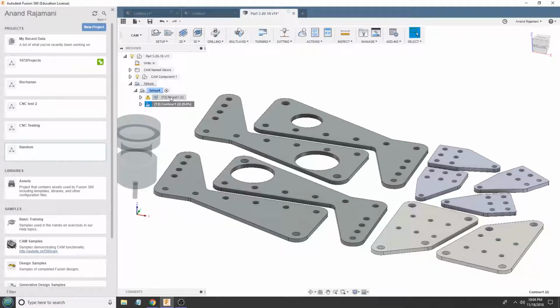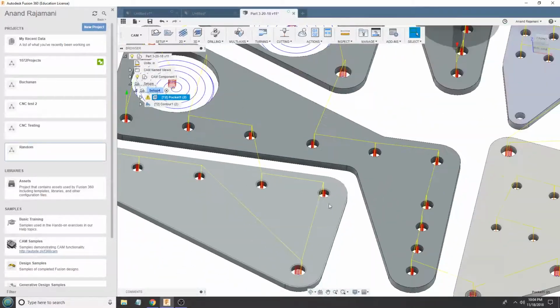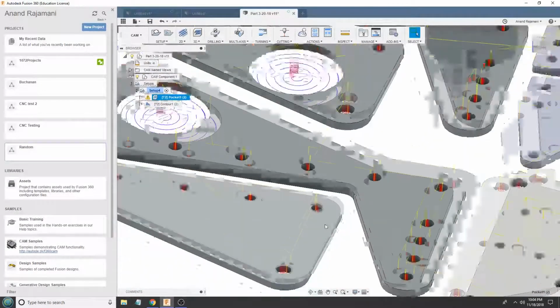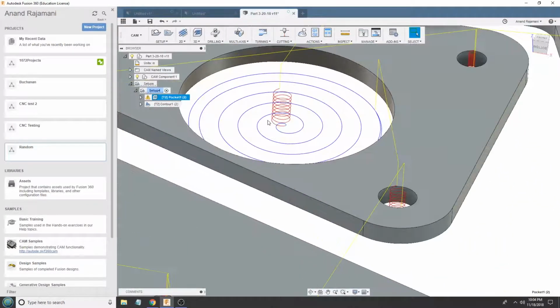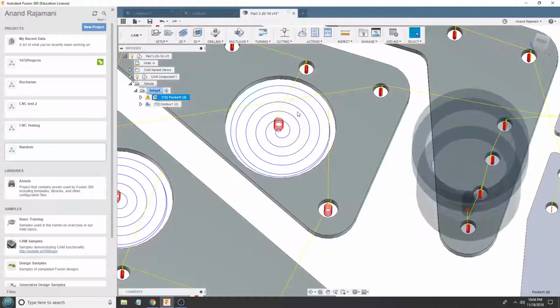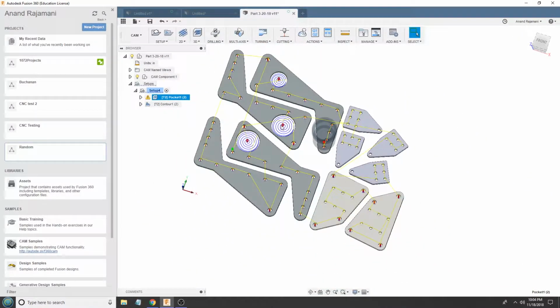So, for example, right here, contour finds all the holes, does a boring operation on all of the holes, or sorry, pocket will do a boring operation on all the holes, and it'll do a swirly kind of more spiral pocket over here, which is fine. I don't really need an adaptive clear for this, and this is probably faster as well for a lot of pockets because I'm just doing rapid moves in air.